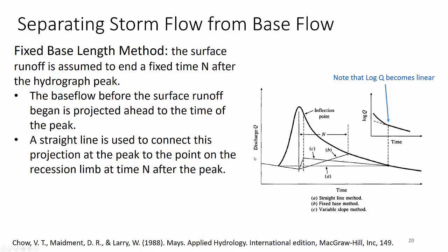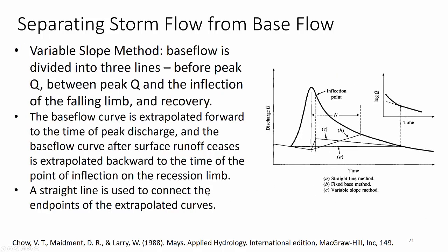So you continue down to the peak flow, you continue your base flow line down, and then go right back up to the flow line where the time period that you defined as the end of the runoff event occurs. These are often standardized in watersheds, but again, if you've got that much information, you've got real base flow information. You don't need to project it. So I don't really understand the utility of it, but it's often used.